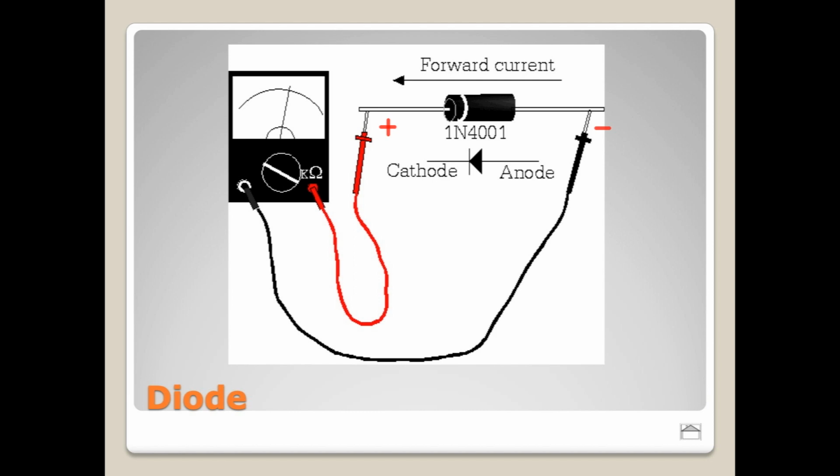I will tell you though, generally speaking, if you suspect a diode like this, it's important to understand how to test them for sure. But if you suspect a diode like this being part of your problem, just replace it. Again, they cost like 3 cents. And this is the kind of thing, it doesn't hurt to have a handful of spares around in a tech shop to be able to just swap it out and see if that fixes the problem.